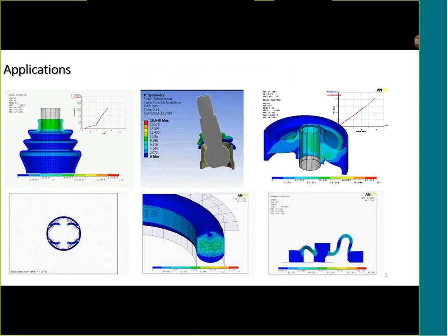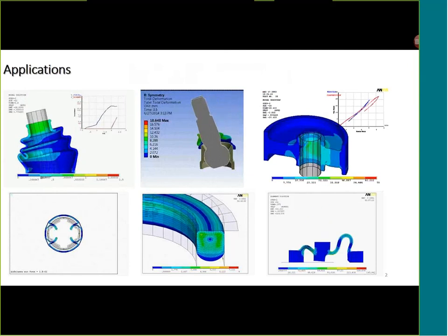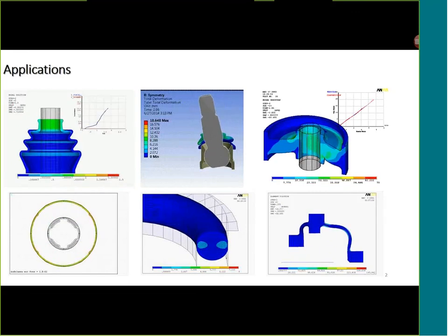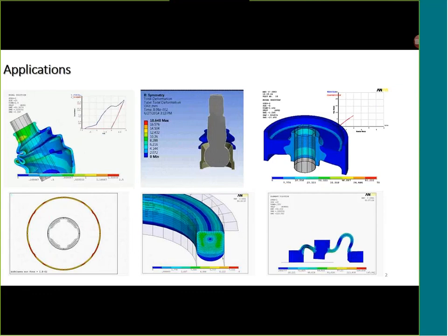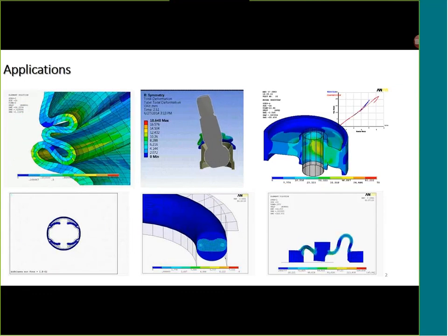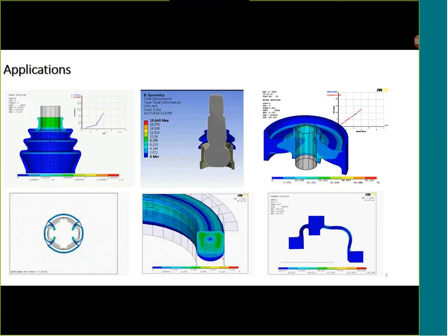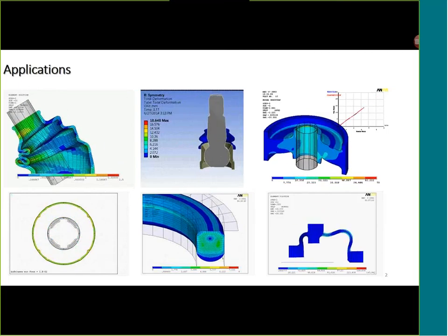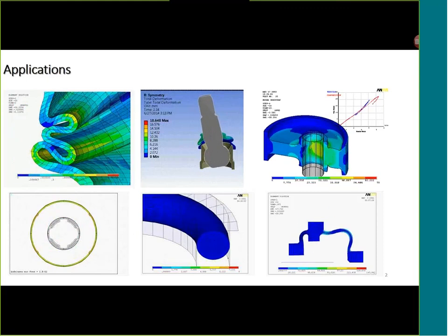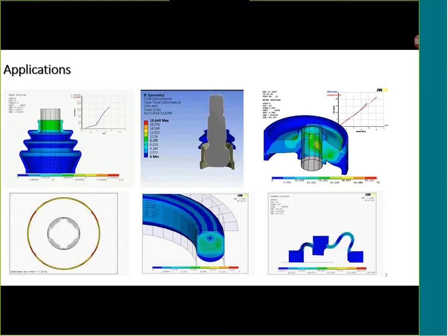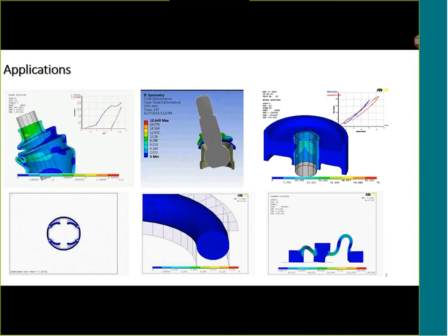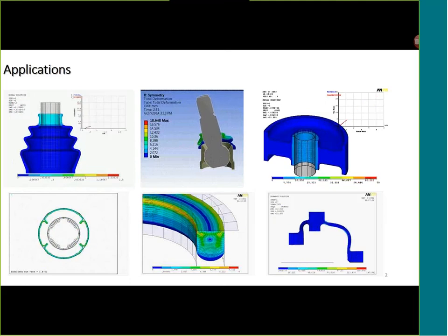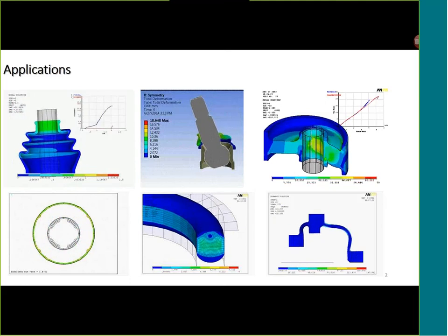Elastomeric components are part of the many practical product designs that are being made. Elastomers serve one or many purposes in the products that are being sold to customers. Either they introduce some flexibility between the components, or they serve the purpose of sealing. In some places, they also serve as a vibration isolator. In some places, they act as a non-load carrying member, such as a dust cover, etc.